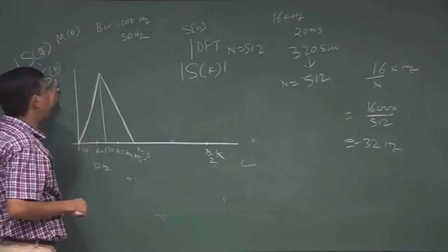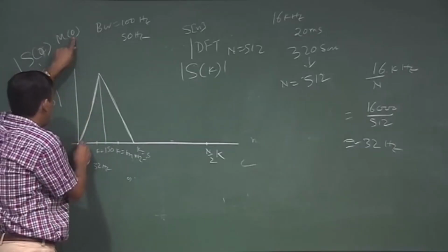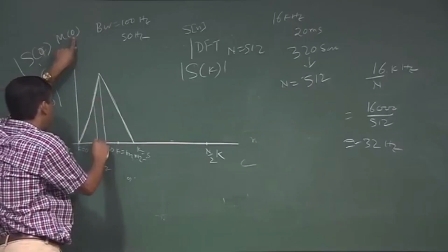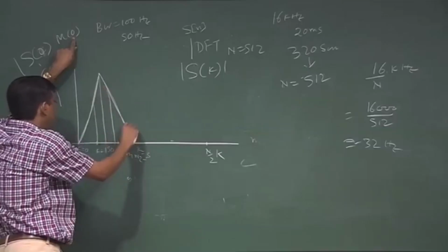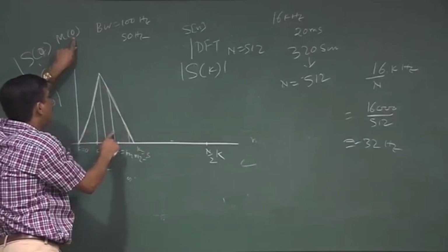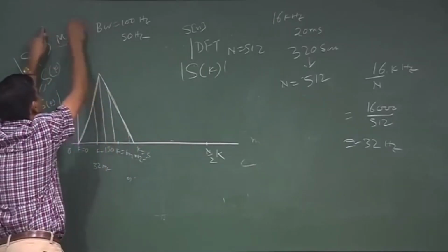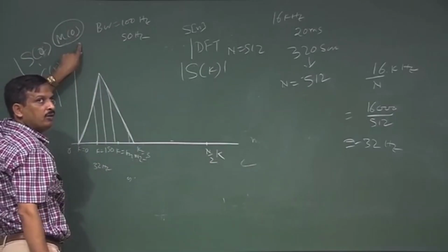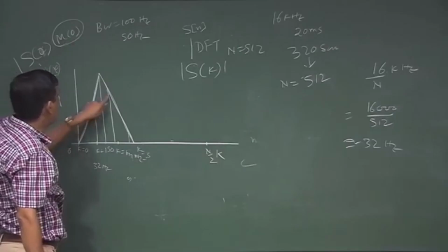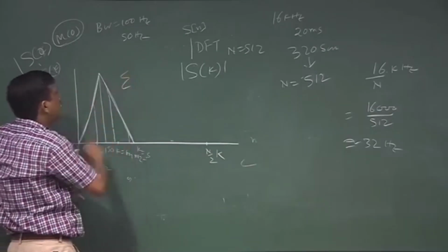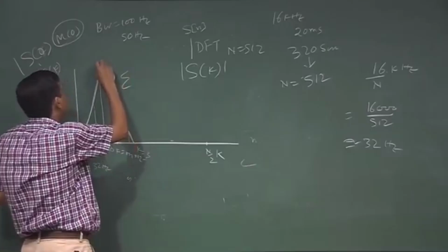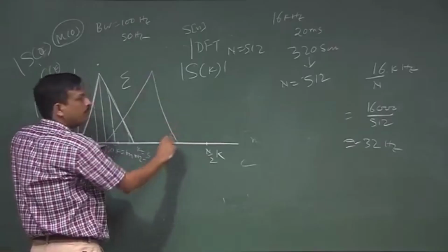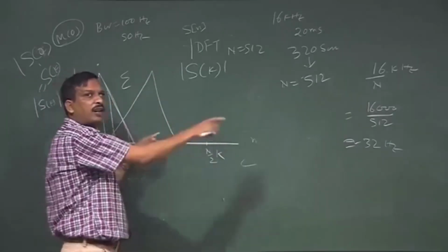So, the original spectrum is multiplied by m0. What is the m0 coefficient? It is 0. Then I can do k equal to 1, then k equal to 2 and then k equal to 3. All those will be multiplied by the m function. So, m is called the filter weight function. That filter weight function is multiplied by the individual power, then I take the sum and get this point. Next, I design another filter with 50% overlap. That way I can design the filters.